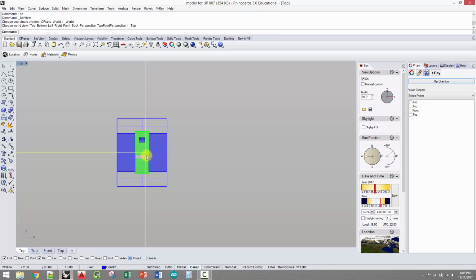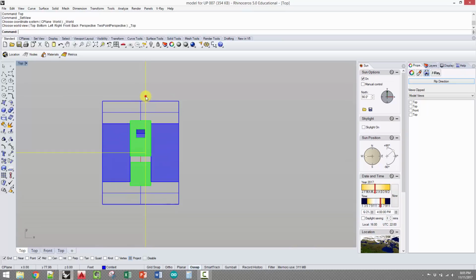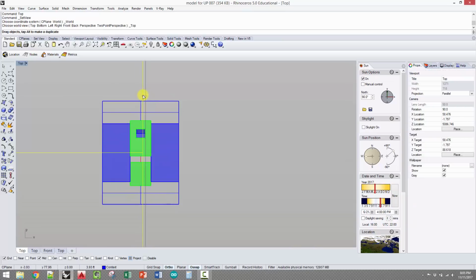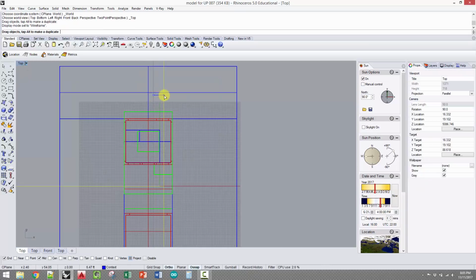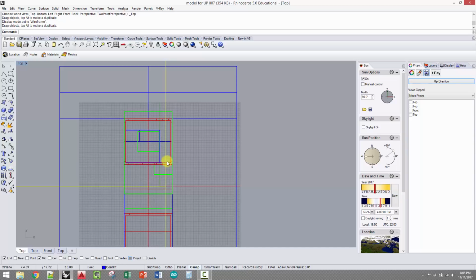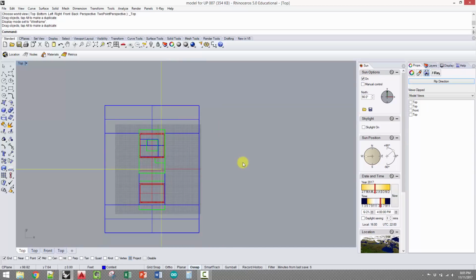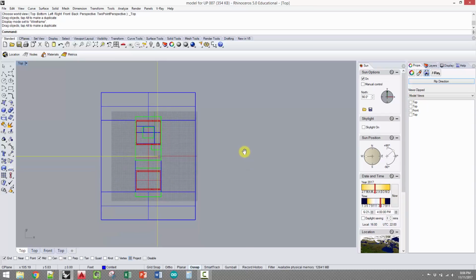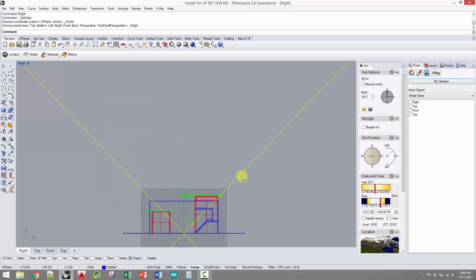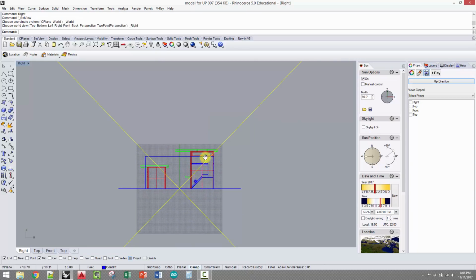Now, if we want to move it to a different kind of section cut, you can go ahead and pull that any way you want to. I'm going to wireframe here. I'm going to pull it because I want to actually clip my stairs here, because that's a nice section. You could clip it through things like skylights. Anywhere that you get a really spatial section is definitely what you want. And then to get the view in this case, and your mileage may vary, I'm going to go to right-hand view. I got my clipping plane here.